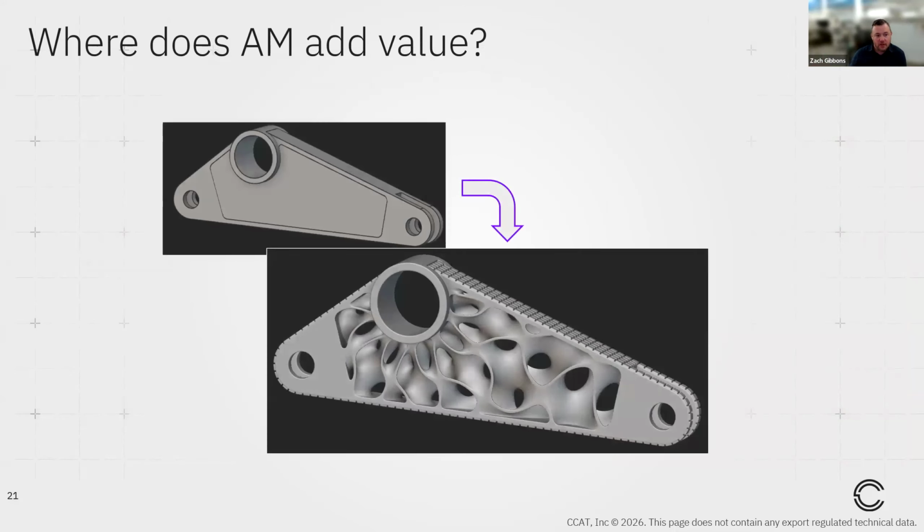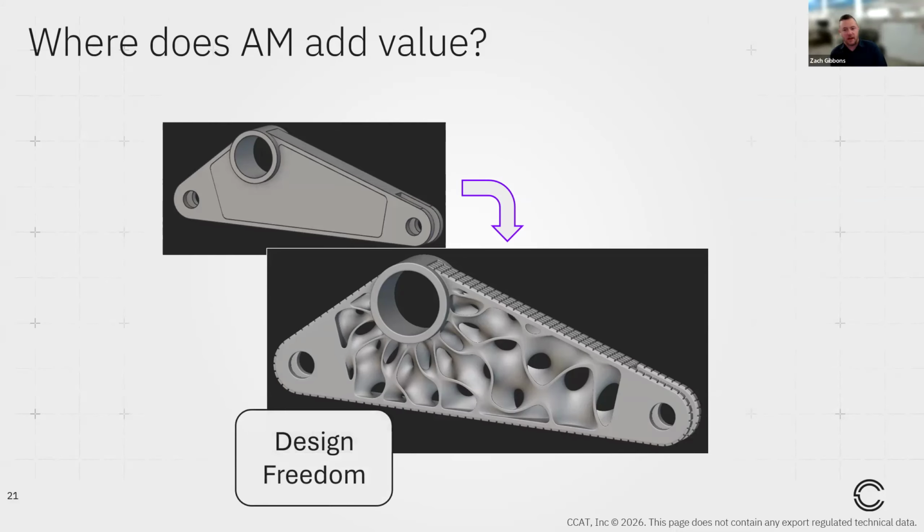First and foremost, I would say is the ability to design geometries that we largely could not manufacture other ways, or at least not manufacture them easily. And I'm going to loop that into the term design freedom, right? So we have a whole new freedom we get with 3D printing in terms of the different shapes, geometries we're actually able to create using this printing technology. But there are a number of other ancillary benefits which might not mean too much today, in a college engineering course, but when you find yourself out in industry working for other manufacturers, things that definitely hold a little more weight.